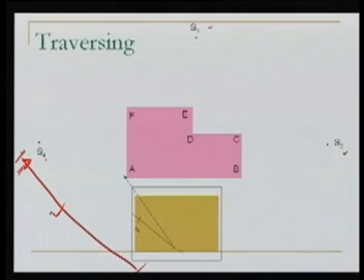So we measure this distance, and then we plot this point here. So this S4 is plotted. Then next, I am drawing a resector to the corner A, then to a corner B. Right now I am not plotting this A here, because I am not measuring the distance from S1 to A. Similarly, for B also, I am just drawing a resector.